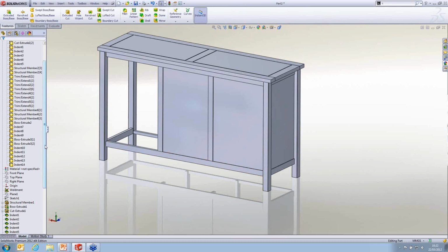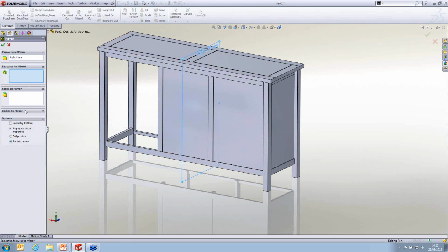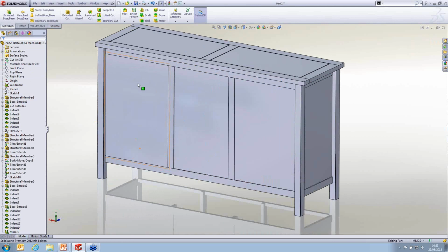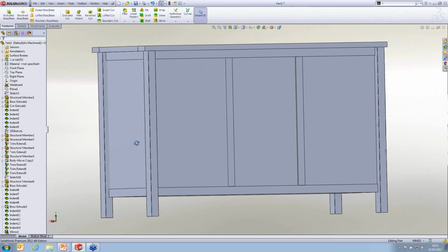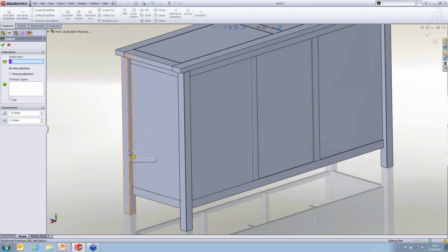Now what we can do is mirror across the two that we know are the same. So because of where we positioned our rectangle at the start, we can leverage mirror. So here we're going to mirror this body and this body over to the opposing sides, which gives us the two panels there as well, and then we can use our indent tool again to do these.